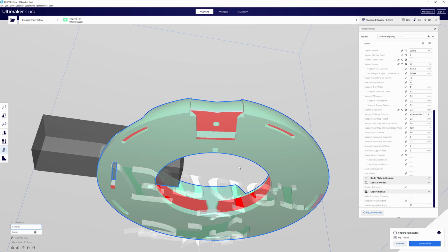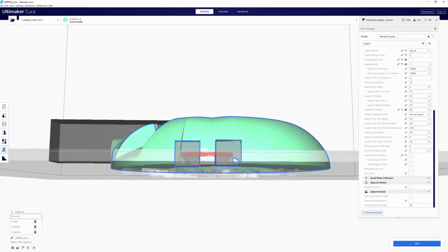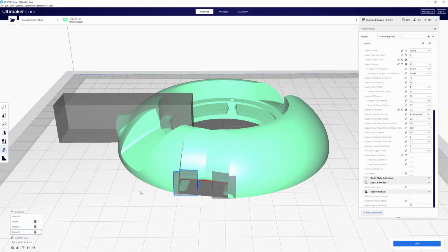This one's a little bit tough. When we print these cones, we just get away with 2 support blockers. And that's just to cover this little area underneath kind of this dovetail shape that keeps everything in place, so that we don't have supports going all the way across here. It's good to have some, but we're going to use the blockers to keep that area clear and easy for the support to remove.